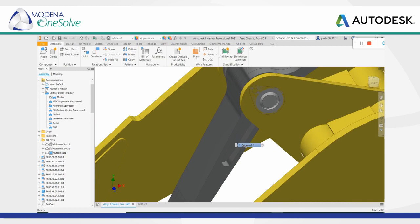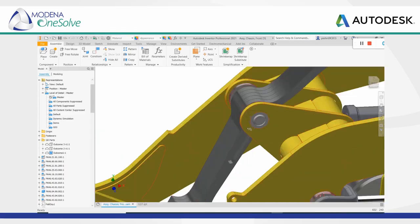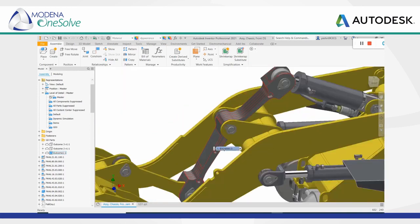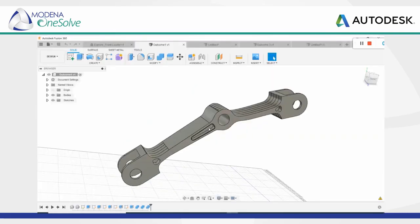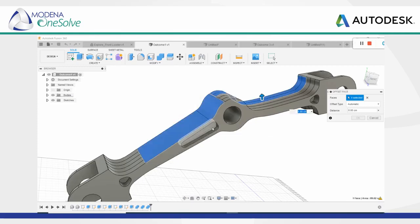Now, if you have a look, we've decided on this design and we'd like to make some changes to it. So with this workflow, like I said previously, it's bi-directional, so any change made in Inventor will reflect inside of Fusion 360. So what we're going to have a look at is maybe we actually want to lightweight this component a little bit more. We find that we may have reduced the loads that are going to be subjected on it. So I can head over to my Fusion workspace and make those design changes very quickly. What I'm going to do is cut a hole through this component directly from Fusion 360, cutting all the way through this arm.